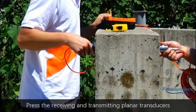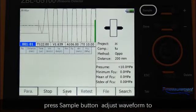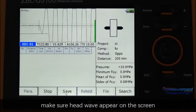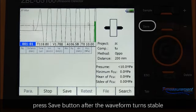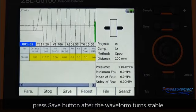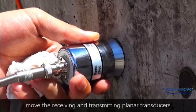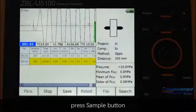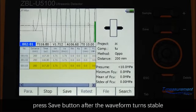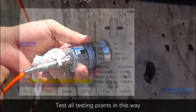Press the receiving and transmitting planar transducers on the first pair of testing points of the component. Press the Sample button. Adjust the waveform to make sure the head wave appears on the screen. Press the Save button after the waveform turns stable. Move the receiving and transmitting planar transducers to the second pair of testing points, press the Sample button, and press the Save button after the waveform turns stable. Test all testing points in this way.